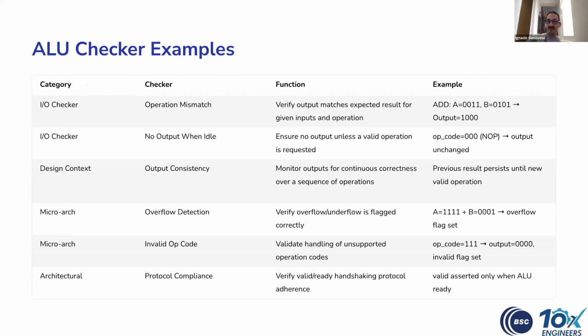Yeah, you are right. I also tell the engineers to look at the design and to try to think about the designers. What did they try to do? What did they assume? And on those assumptions is where we usually find bugs. If the designer, for example, assumed that two signals would never be high at the same time, that's exactly what you should test. What happens if those two signals are high, or what happens if they are not high at the same time.